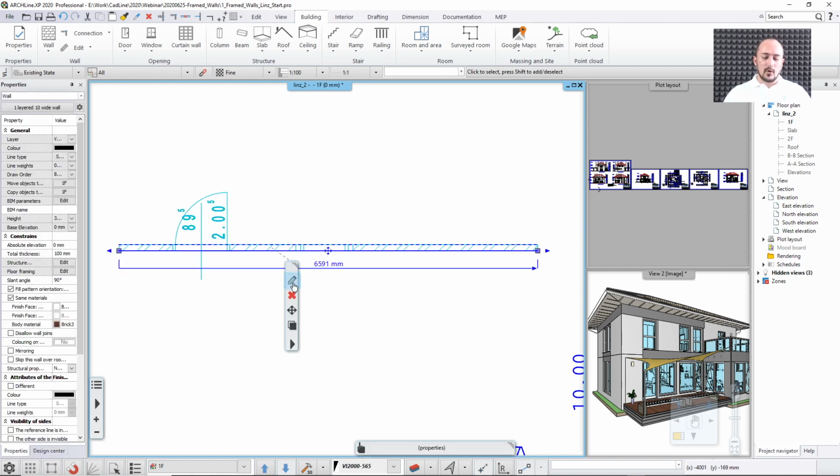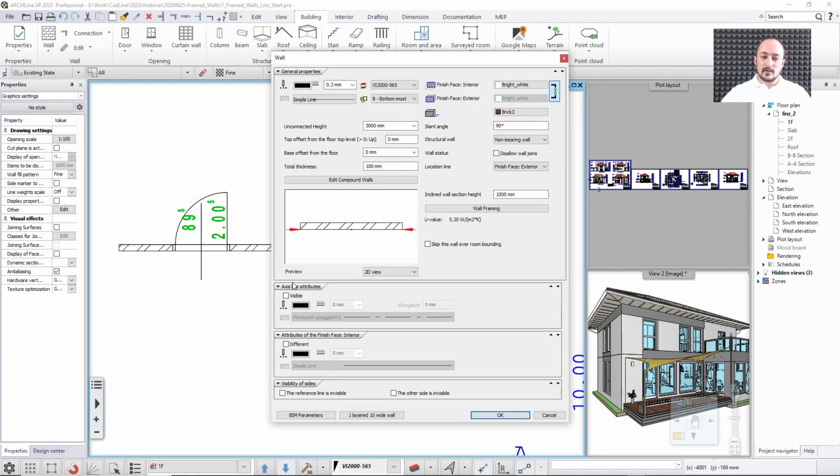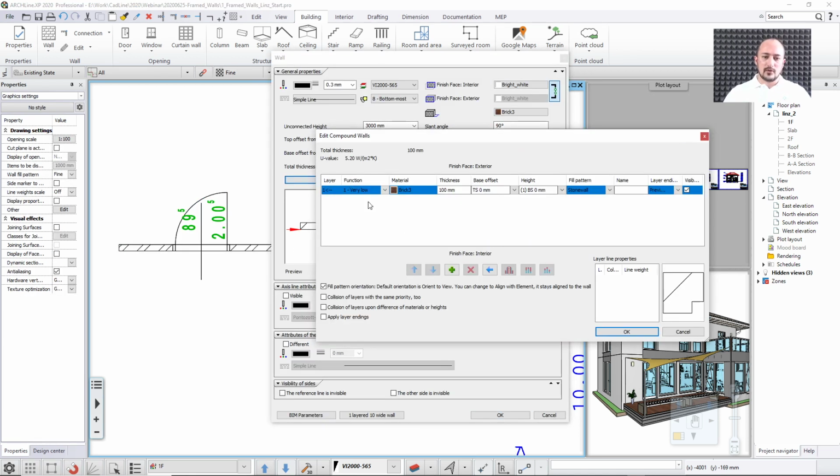Now this wall, in this specific case, will be a partition wall which has the main layer. It will have thermal insulation, and on the two sides I will use some sort of plasterboard or something like that. So I will go into the details and start detailing it. Let's say that I have 2 more layers. I will insert 2 more layers into this one.